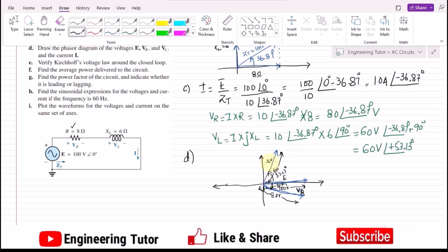So this is the phasor diagram for the voltages, but now we also have to draw the current here as well. For drawing the current, let me use this green color. The current here is 10 amps, and the angle with it is 36.87, so that is this one. Let me write it like this. Okay, so this is the current.